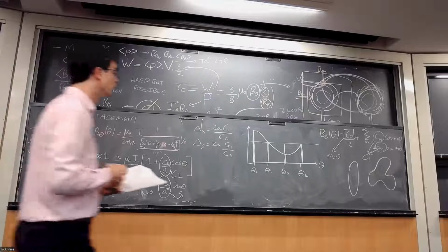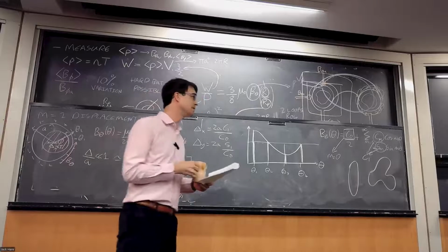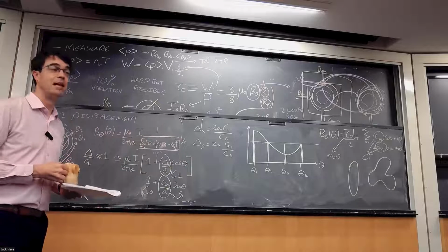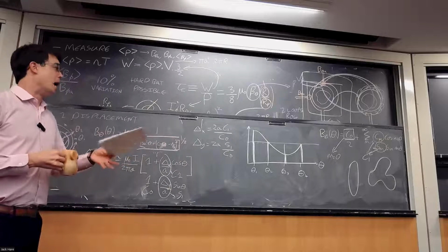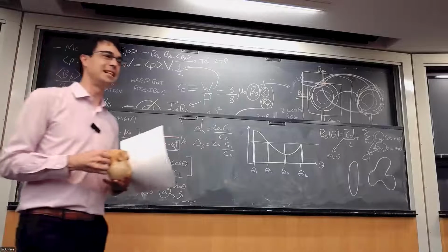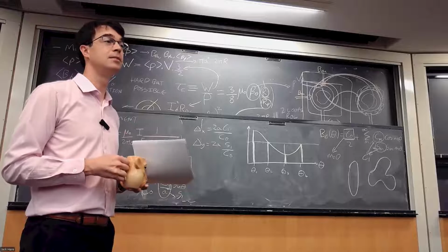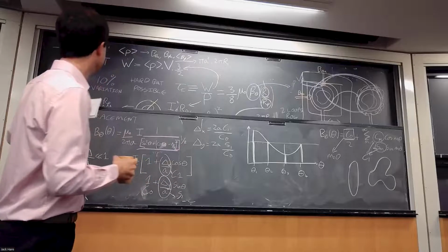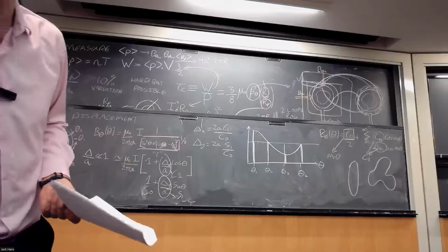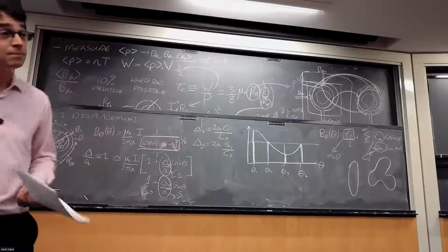Yeah, so the question was, at what point do you need to start worrying about eddy currents in the vacuum vessel messing up this measurement? These would definitely be affected by eddy currents, right? So that's like a higher order correction that you need to do to understand what the eddy currents do. Yeah. So in this assumption, we have assumed there are no eddy currents. We have a non-conducting vacuum vessel or something else like that. Yeah, exactly.